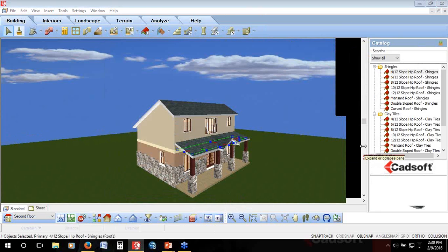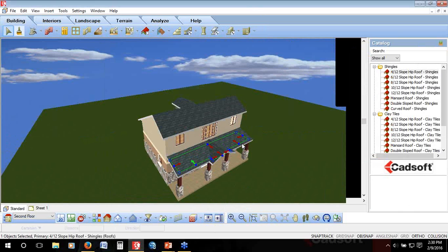So let's go over there and see our questions. If you wanted the front porch roof to have gutters on the front and both sides, you would only select the side against the house to be a gable, correct? Yes, that's absolutely correct. So if I tilt this down a little bit so we can see the arrows forming here, if I wanted this side and this side to be hip ends with a gutter along that edge, I would have left them at hips.